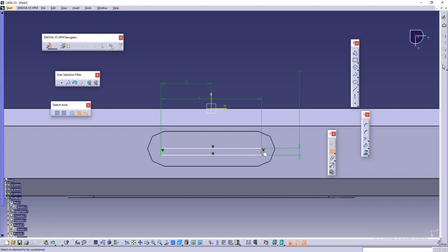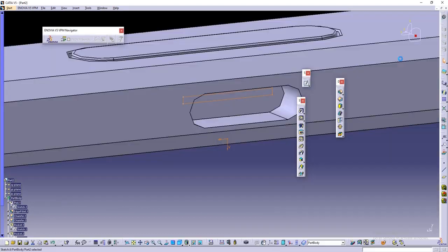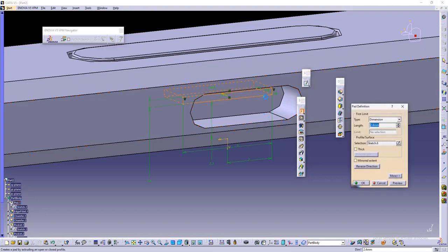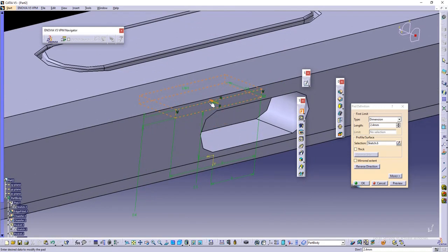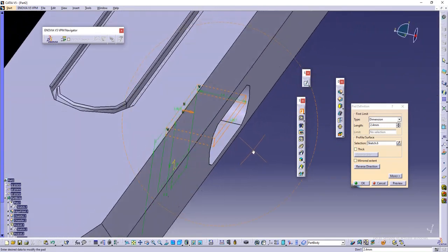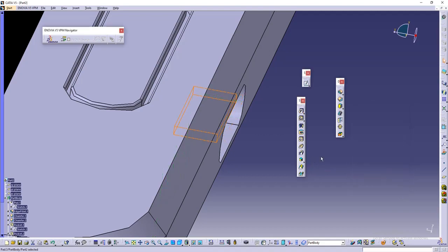And the next thing we want, you already given, and let's give some 2.3. Go back to the sketch. Now pad, now it is in the inside direction, right? So the trick here is always check where the arrow is going. If you click on the arrow, it will turn in the opposite direction. So it is going out, so maybe a little bit inside, not this much. So maybe we'll manually change it from 2.2 to 1. Let's see the preview. Yeah, this will do.